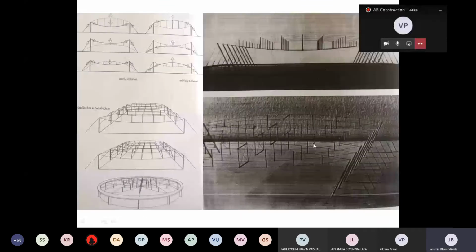Yeah, you can see them here. You can look at how 2 cables, so it's a kind of a lightweight truss in some sense. The only thing is that in a truss, because you have spans such as these, both the bottom boom and top boom, or the rafters, would tend to get very heavy in order to bring about rigidity, considering the spans lead to the depth of the members.